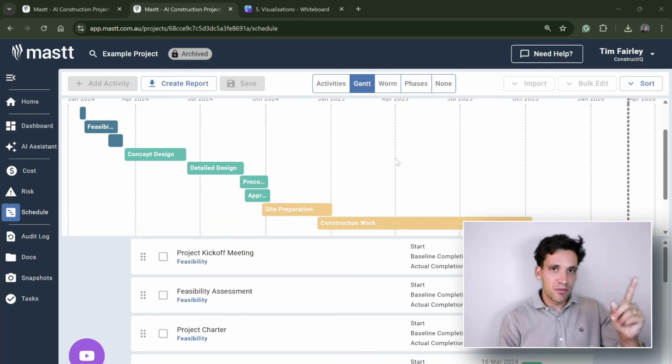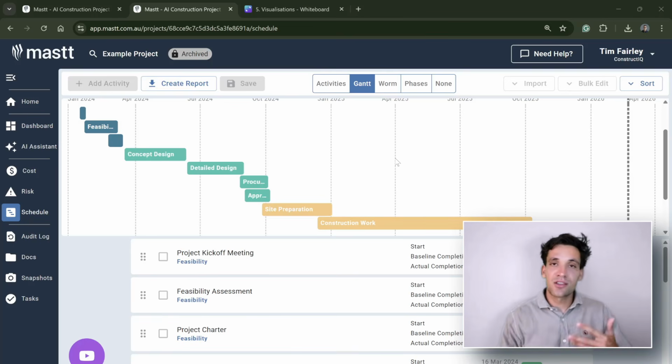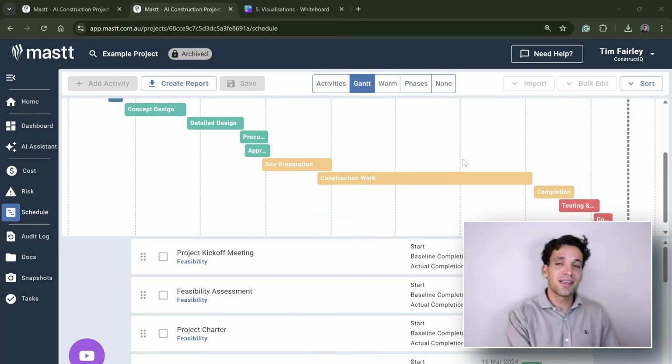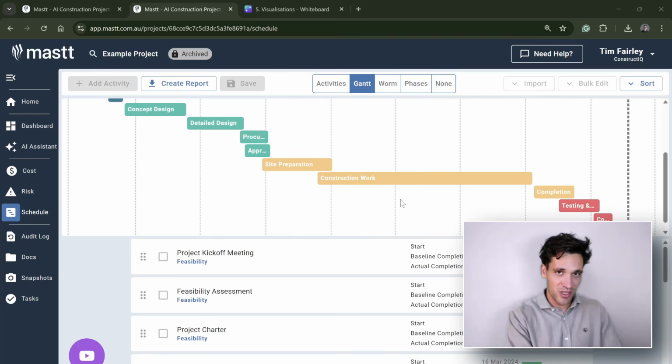Number one are your preliminary costs. So if you're paying for a project manager, an engineer, a supervisor, all these different overhead roles, you're hiring office facilities, the duration of the project impacts the cost of your preliminaries. So any preliminary budget you have, the unit of measure for that is going to be the duration of the project. You might be paying overheads of $10,000, $20,000, $50,000 a week, and therefore the number of weeks left to finish the job is absolutely essential to understand.